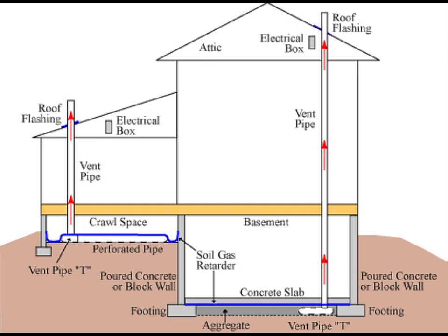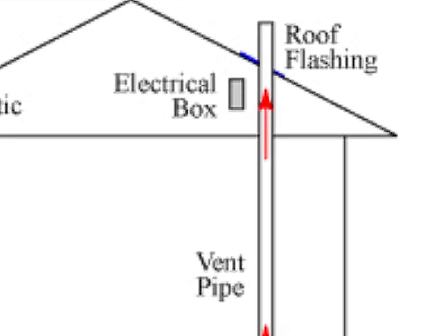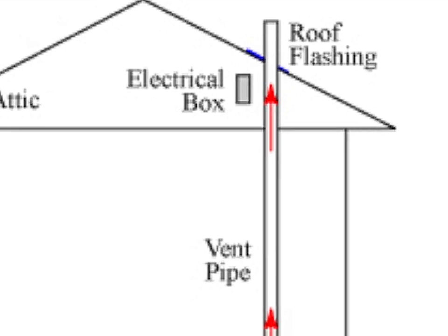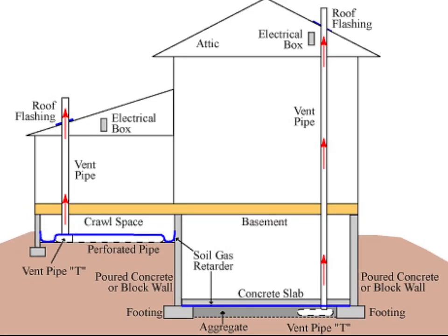Sealing and caulking. Seal all openings, cracks, and crevices in the concrete foundation floor, including the slab perimeter crack, and walls with polyurethane caulk to prevent radon and other soil gases from entering the home. The installed system is initially passive, but it can be made active with the later addition of a fan. To this end, an electrical junction box with an outlet must be installed in the attic near the radon vent. This will be used later for a vent fan should, after future radon testing, a more robust system be needed.